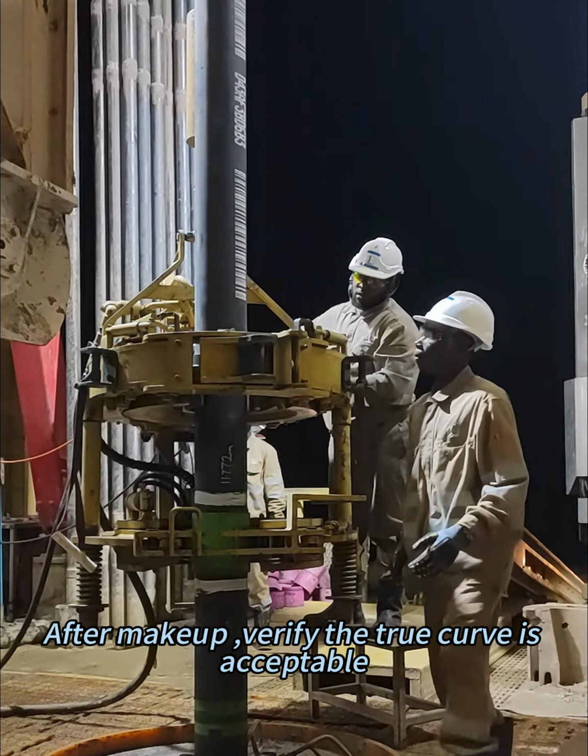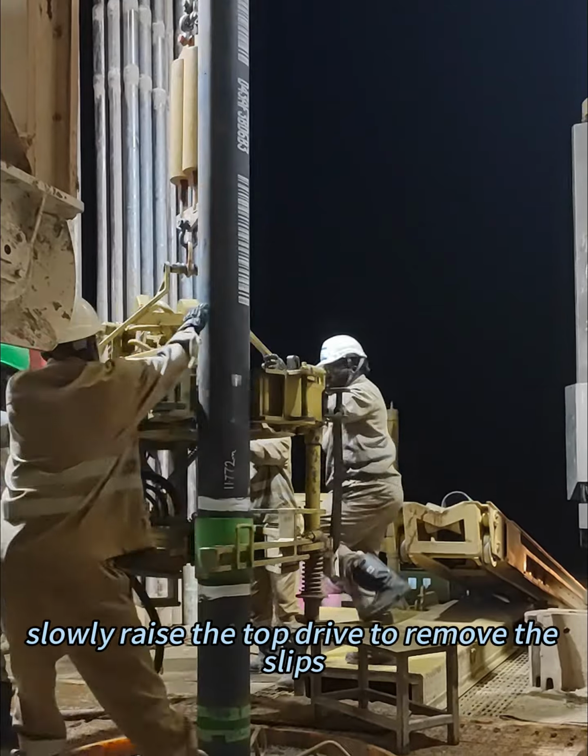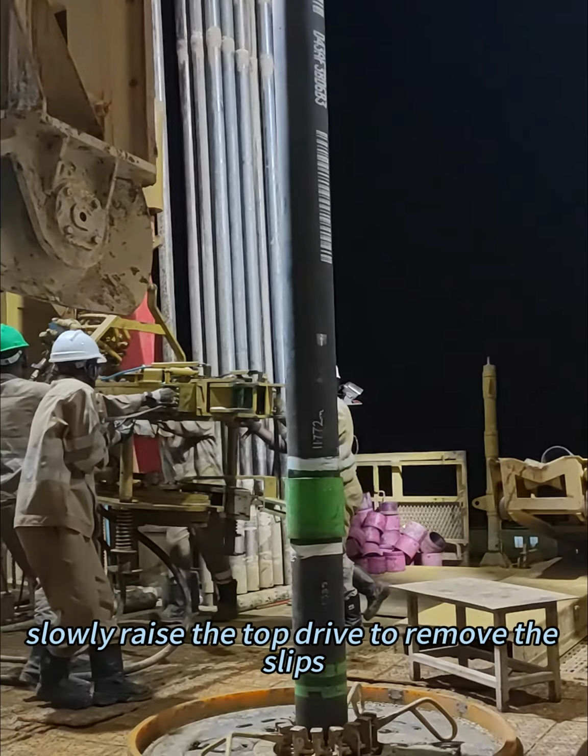After makeup, verify the torque curve is acceptable and retract the tongues. Slowly raise the top drive to remove the slips.